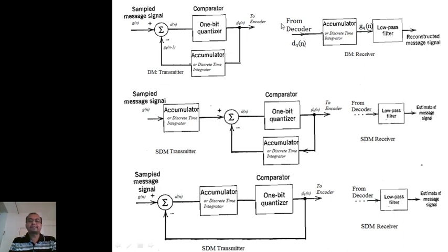Now this is a linear system, so whether I place this accumulator at the beginning, ahead of this block, or after this block, it will not affect the performance. So let me place it here. Now see, this Gn is multiplied by the transfer function of this accumulator, and whatever signal comes here is also multiplied by the accumulator in the feedback path, which then generates the Dn. So there are two accumulators. Can we do something to replace them by a single accumulator?